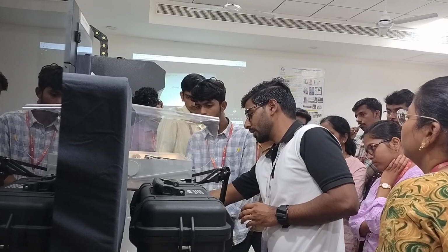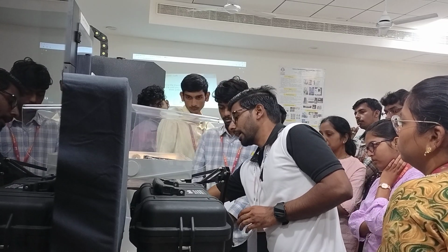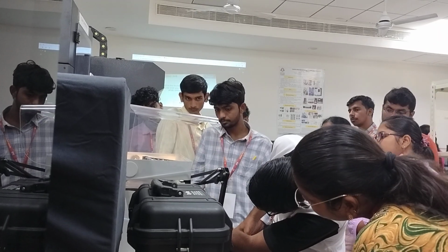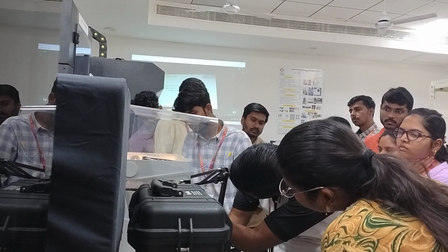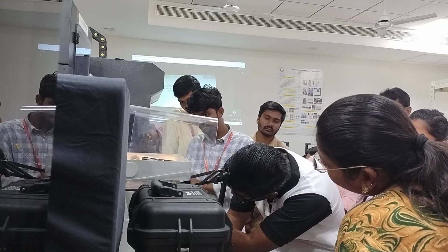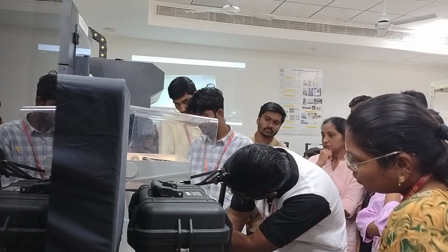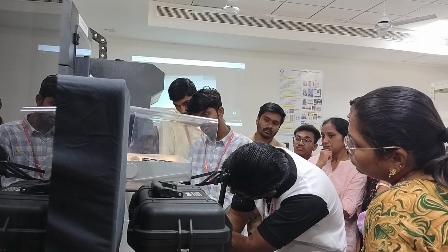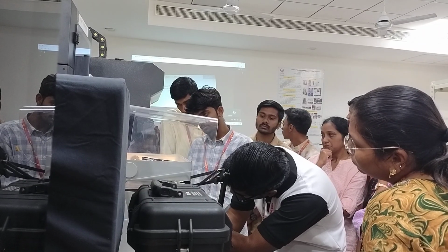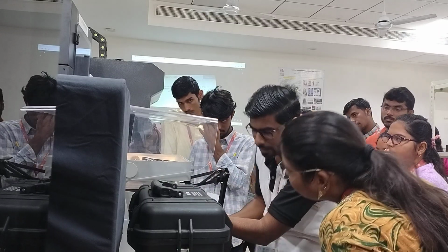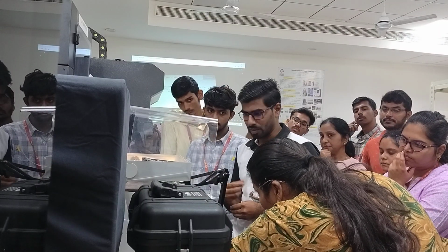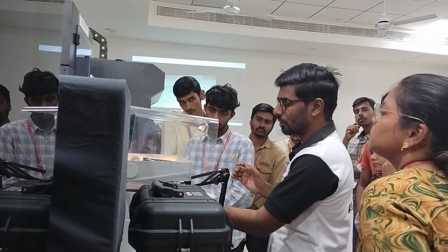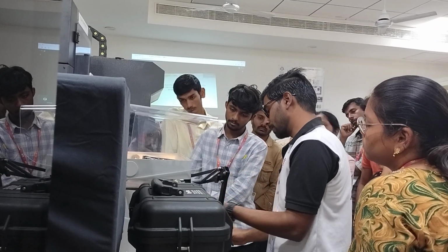It is moving to the left position, sorry. Again, the same thing we'll do here also. I'll put it between the nozzle and the bed and I'll screw it. I'll continuously move it so that I get the exact clearance. One of you can just move it and see if you're getting some resistance. There is some resistance, right? That is the resistance we should have. It should not be very tight, neither should it be very loose. Then I click on next.